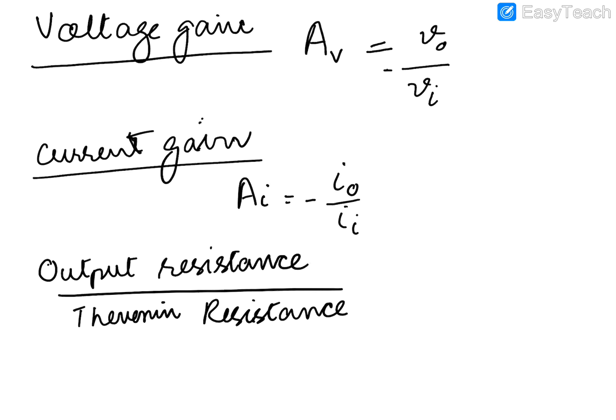So you can measure the Thevenin resistance at the output terminal by using two methods. The number one is you connect an external source. So in this case, when you connect an external source, and then you will short the voltage source on the input side. Here the Ro will be equal to V external, which you have connected, divided by I external.